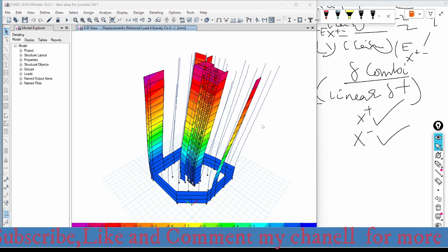So next time I will try to show you the application of the notional load using the manual method. That means the notional load will be calculated manually and applied at the nodes of every vertical member, so that we will see its effects and compare the results with the results obtained by the automatic consideration of the notional load.